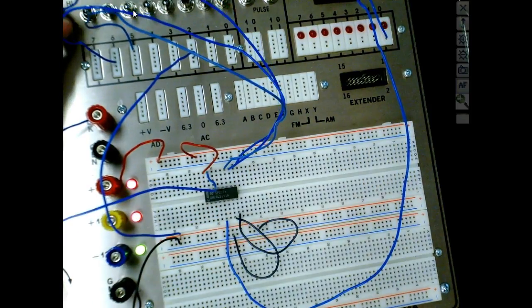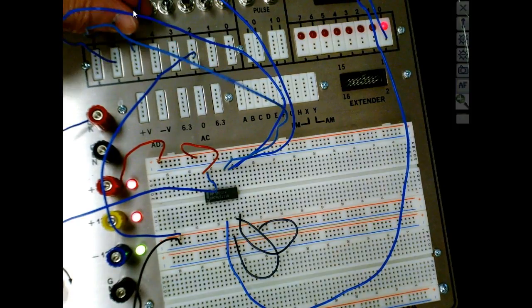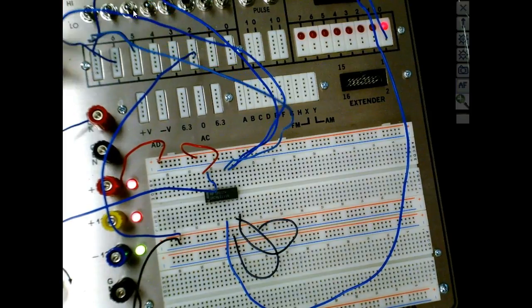Okay, it starts flashing. So an open select pin: on this chip, all your inputs, if you leave them floating, they're accepted as a what? A high. Y'all understand what the term floating means? It means it's open, right? Any more? So that would answer number 3. What does number 4 want us to do? Now open 1 or 2 address pins and check the output logic again. What effect does an open one of the 3 address pins have? So that's your select pins.